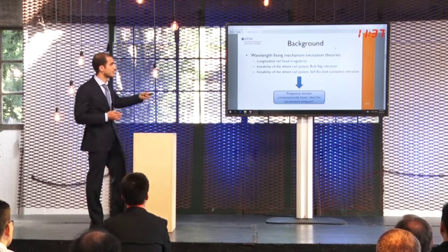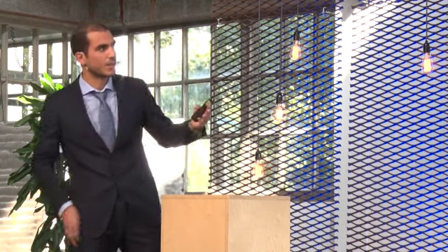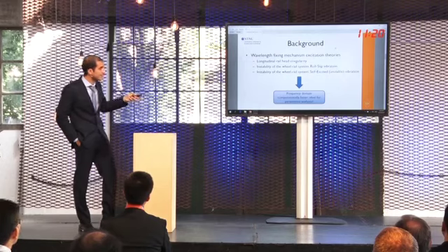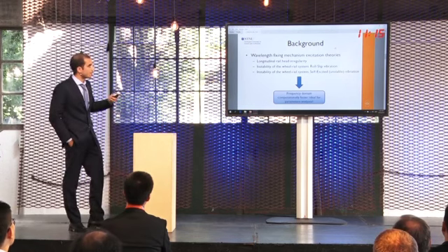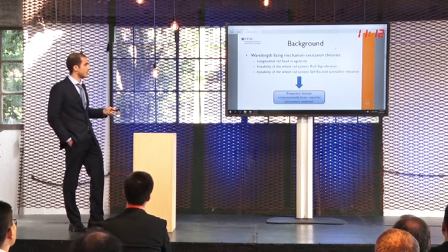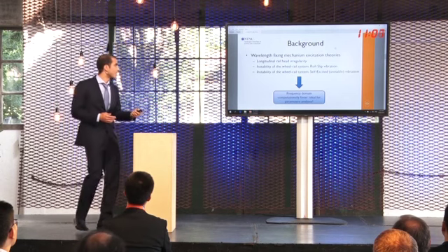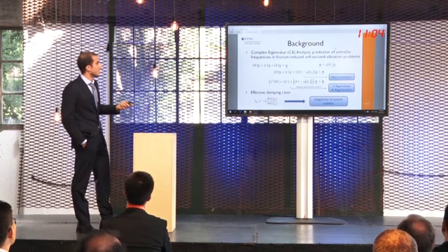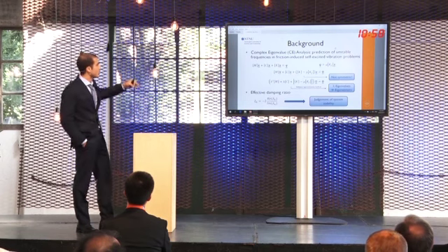There are two points of view. The first one is in time domain, which considers the roll-slip vibrations. And the second one is in frequency domain, which considers the extraction of the self-excited vibrations of the system. Since this latter case is computationally faster than the other one, since it's in frequency domain, we have decided to use this one in our analysis, because we're going to be dealing with parameter analysis, so it's very much an effort computationally.